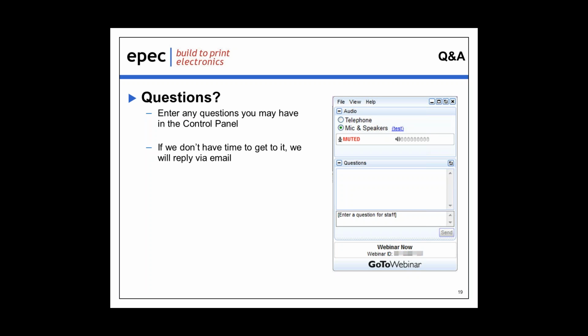Another question came in. If an assembly is already designed in, is it worthwhile to look at the components to establish whether they are correct for the application? Good question. I would suggest that if there's ever going to be a rebuy or a redesign or anything having to do with the system, I would review the cable assembly just to make sure it does comply with the latest standards. RoHS, for instance, comes out with modifications every couple of years. Things are changing. So whether you redesign the assembly or the components of the assembly really depends on how old the original design is and whether you feel that it'd be worthwhile to explore any changes at that point in time.